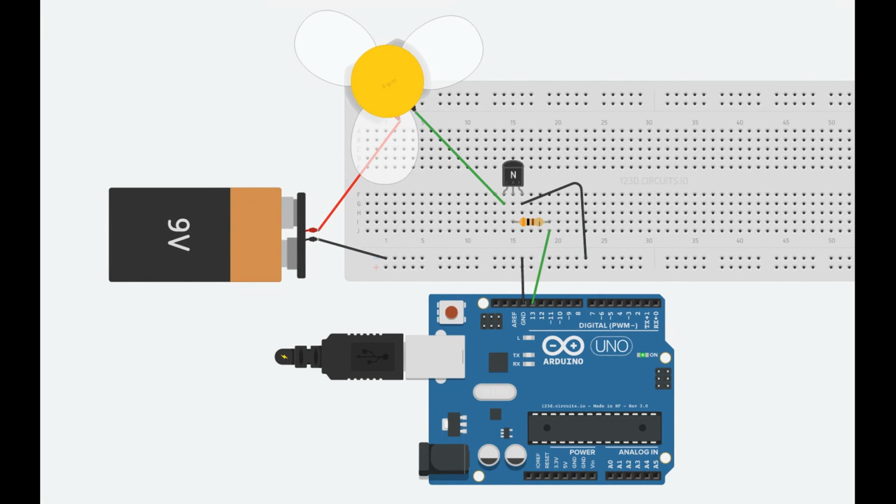And this is what that sample would look like if we were to wire it up with an Arduino. This is running the default Blink sample code, which you can find under the Arduino file menu, under examples. I changed the battery to 9 volts because this is a more standard and readily available power supply that you might have. And I'm not really sure what the specifications of this motor are, but you get the example. Also, we don't need the second transistor here because remember, Arduino should be powerful enough to drive the necessary 10 or 15 milliamps that we need to drive the motor at full power.